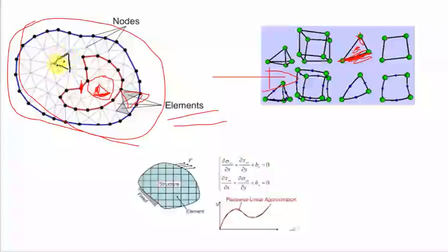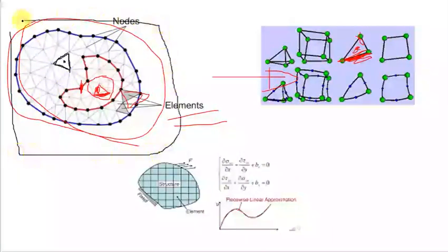Yes, but what we do is come up with an approximation which is nearly there. What happens is that the finer or the smaller the elements, the more accurate the results. So as a designer, if you're breaking your material, you have to break it down into a smaller number of particles.